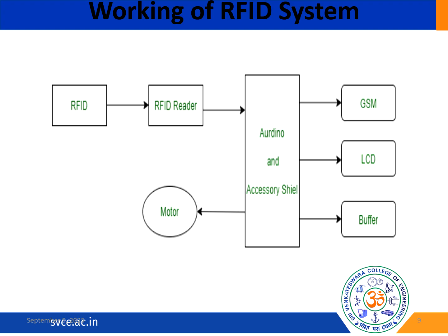Once activated, the tag sends a wave back to the antenna where it is translated into data. The transponder in the RFID tag has a read range based on different types of tags. We have types of readers and RFID frequencies used in the surrounding environment for RFID tags and readers. Tags with a stronger power source also have a longer read range.